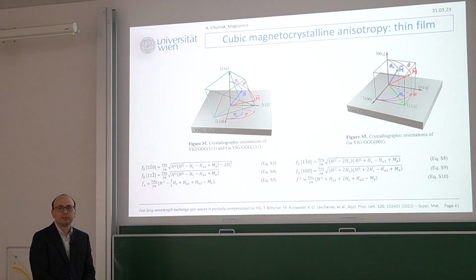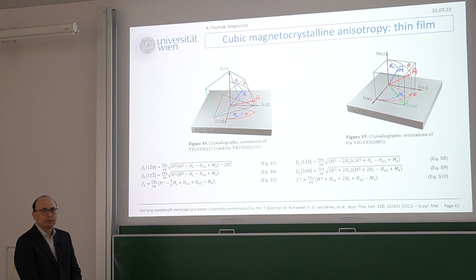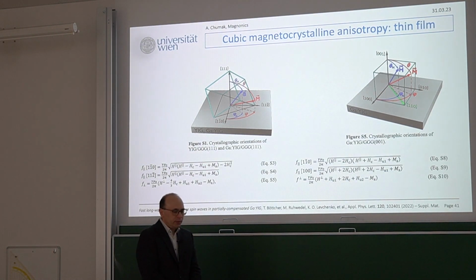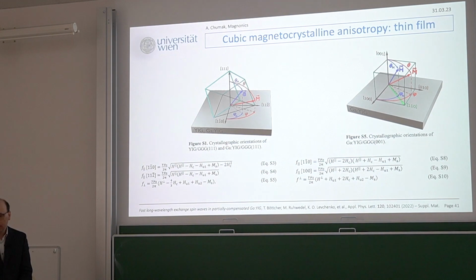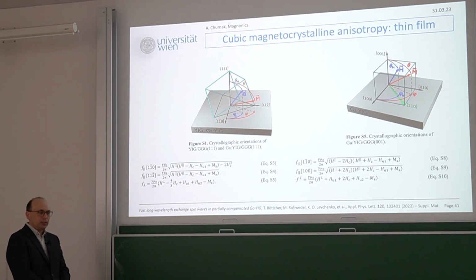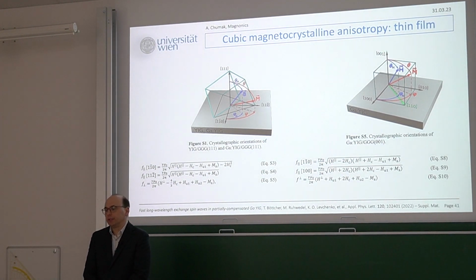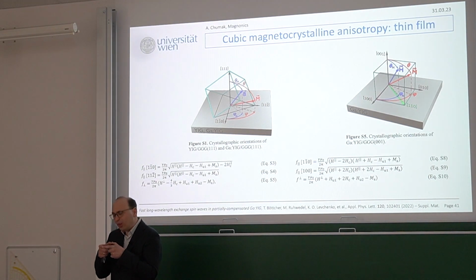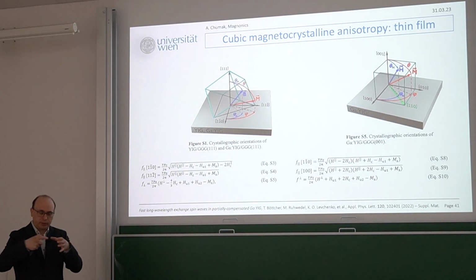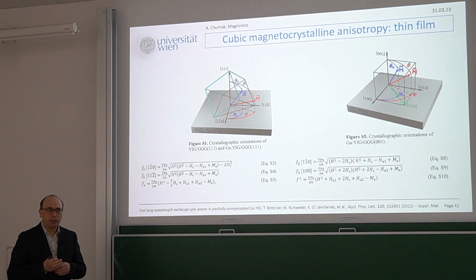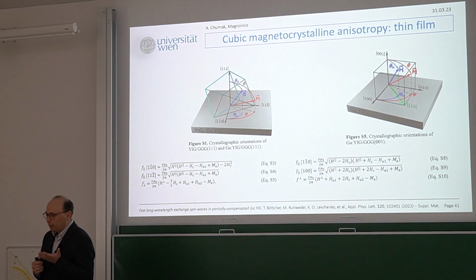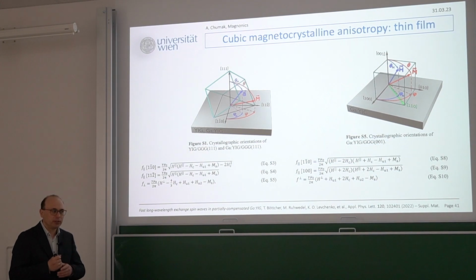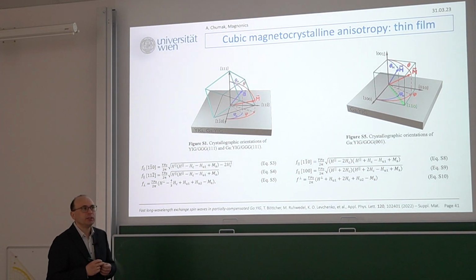And it also varies within one wafer. It can change from, let's say, an outside part of the wafer to the inside. So the question is whether we can expect a change in crystallographic anisotropy depending on which part of the wafer. The answer is yes, we can expect it. The point is that if you do liquid phase epitaxy, thickness pretty often changes: it's thicker at the edges and thinner elsewhere. There can be some contamination. The melted material from which you grow YIG might also not be uniform. Maybe there are some other factors, but I'm not a material scientist, so it's hard for me to answer.